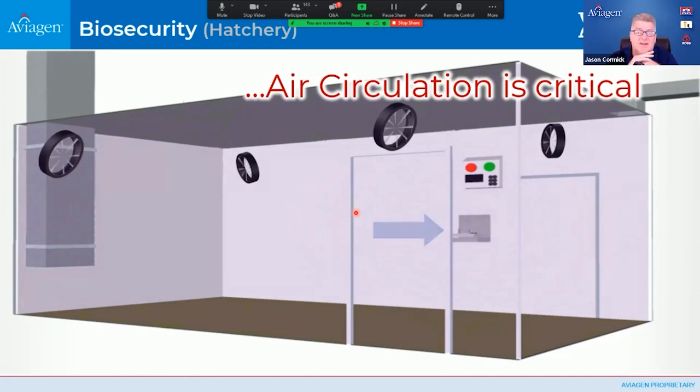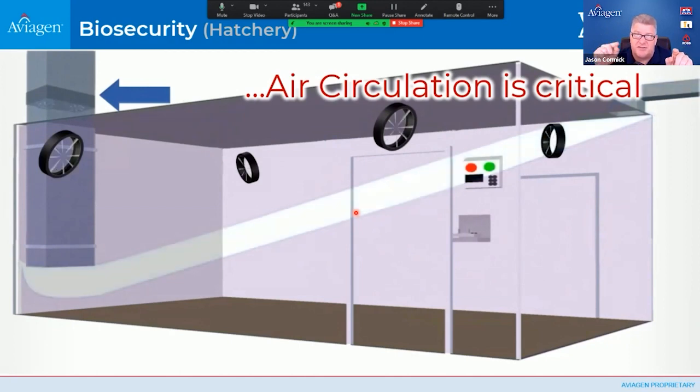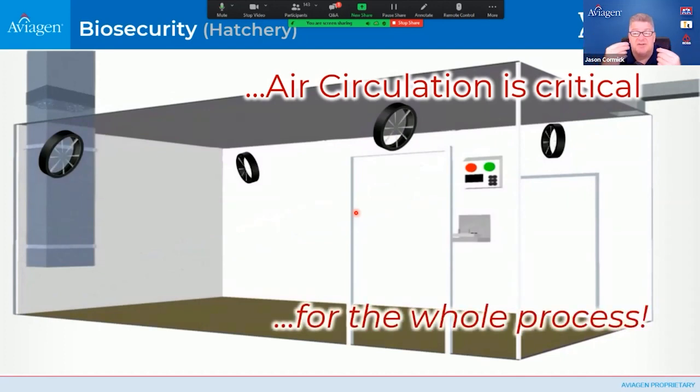It will mix the gas in and push it all the way through the surfaces of the eggs. Now, if you turn those circulation fans off when you exhaust, that air is just going to short circuit straight through to the exhaust point. So we need to make sure that those circulation fans run for the whole duration of that fumigation cycle. That means it's going to clear, so when you go in, you shouldn't smell that fumigant.